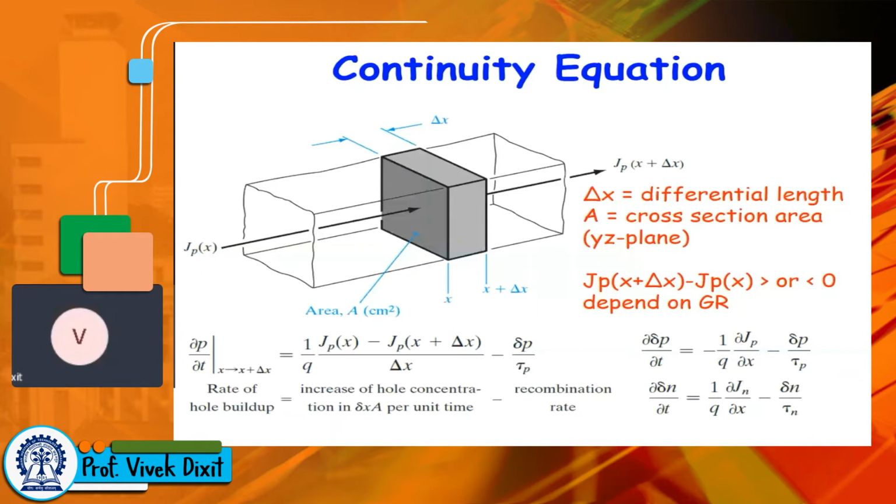Let's say if we have some optical generation, then that generation term will be separate apart from this recombination lifetime. So this recombination is basically based on minority carrier lifetime, correct? So you can write basically two equations, because you can write n is equal to n naught plus delta n, and p is equal to p naught plus delta p.